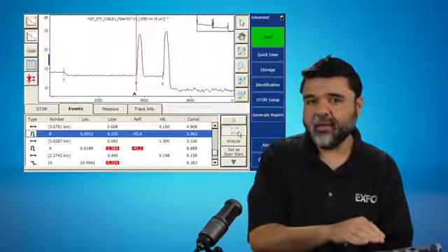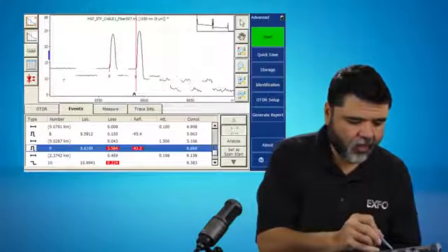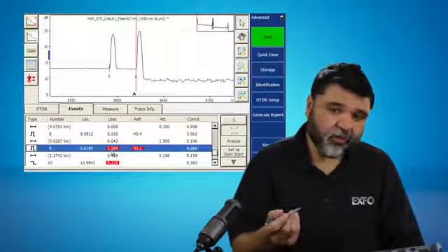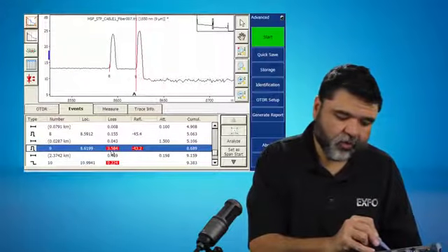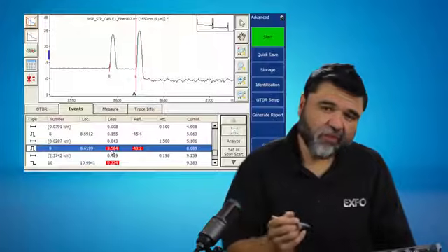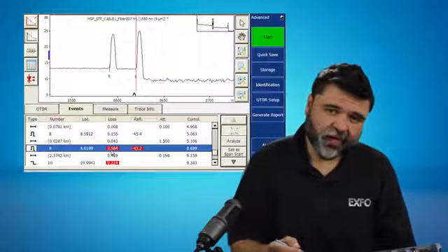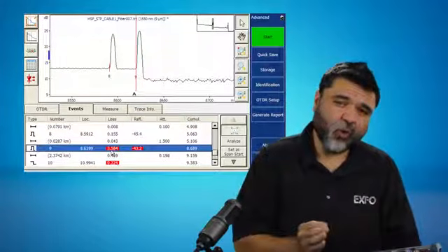This is my bulkhead, or the bulkhead to say the front side of my tie cable. If I go over here, 28 meters away, I have another reflective event. And so this particular one has 3.5 dB of loss, which is clearly a fail, and minus 43 dB of reflection. So the reflection is too high and my loss is too high. I would address this point first.